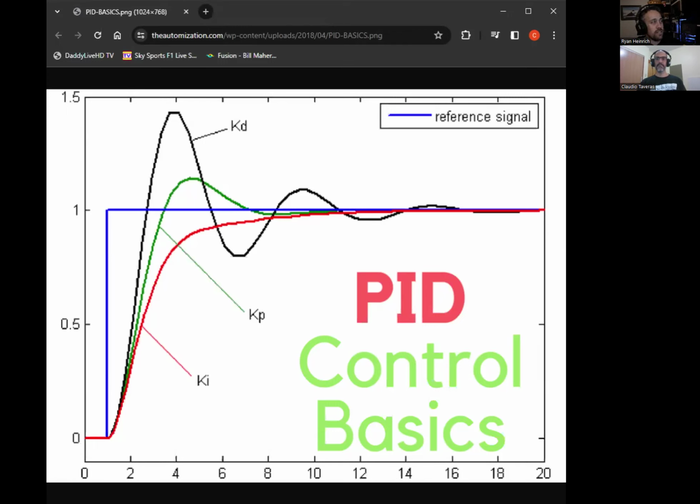Now, if we find that we're still getting this oscillation like the black line after hitting, we probably have too much P. Now remind me, Claudio, I'm pretty sure when we have the integral cranked, we're going to see this oscillation getting closer this way in regards to our picture. Yes, the I makes it really quickly oscillate. So imagine this black line, instead of having 1, 2, 3 humps, the humps will be bunched up. It would be a lot of quick ones instead. So when the I is increased in speed, that's going to be much, much faster and more reactive.